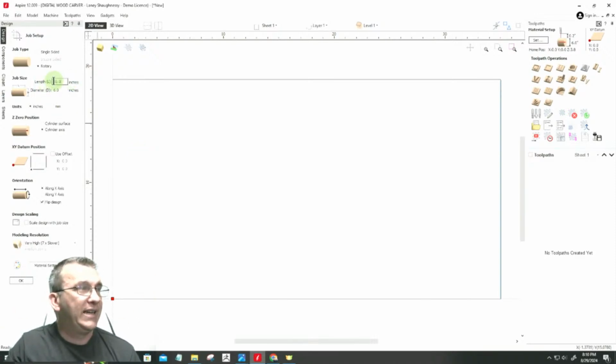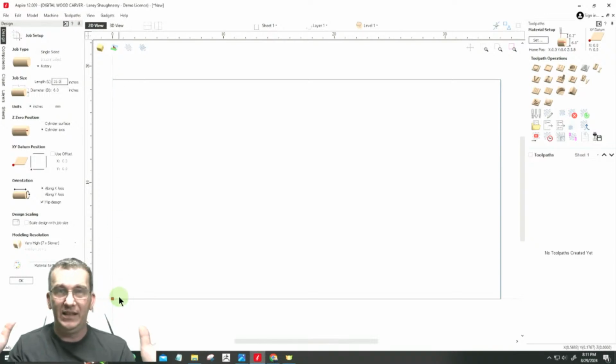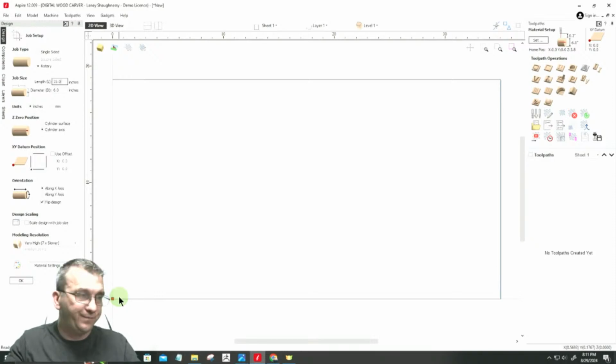Now, if I account for it in my design, then I need to make sure that in my design I mark and lay out for that 1/2 inch of waste on each end so that my design falls correctly in the drawing, and the ends don't get milled.